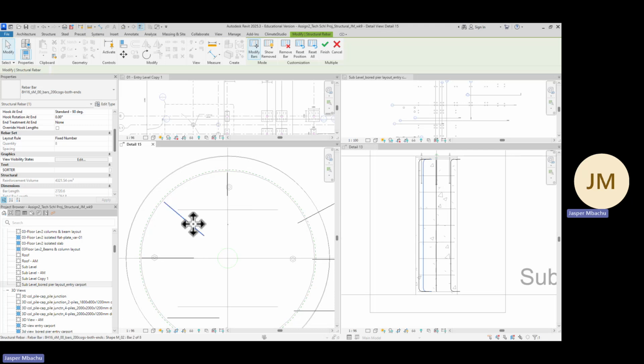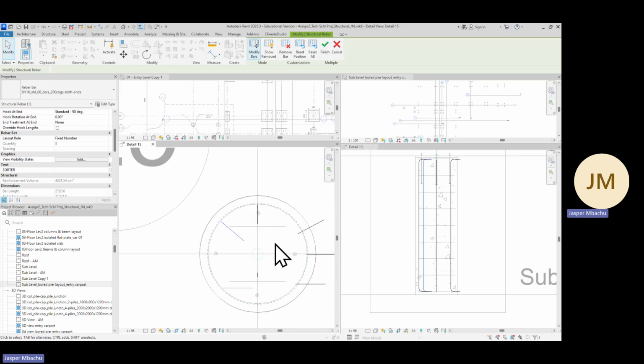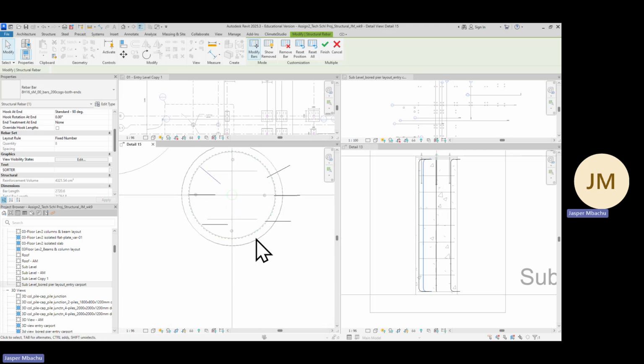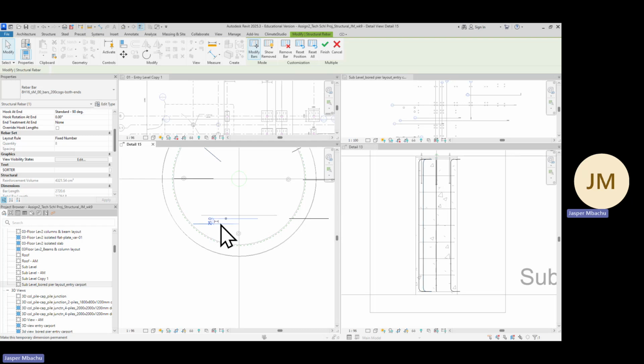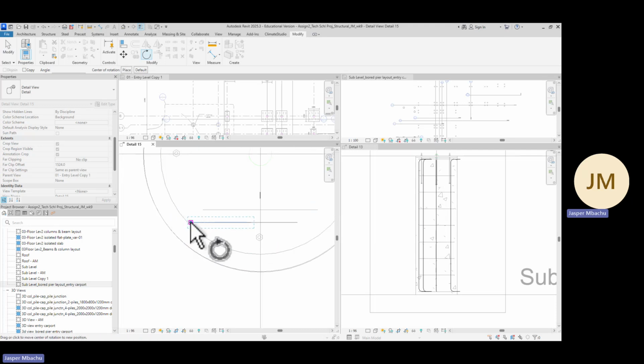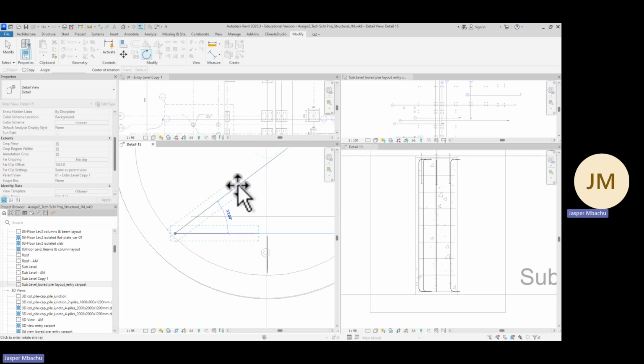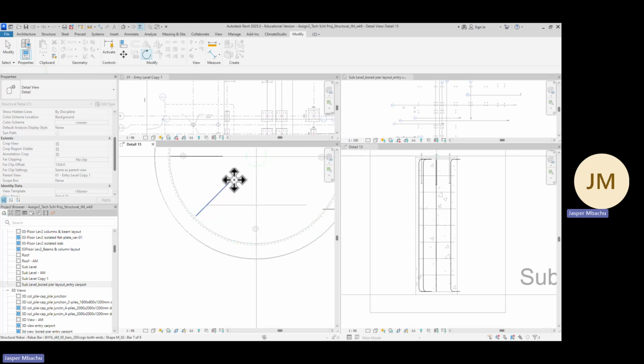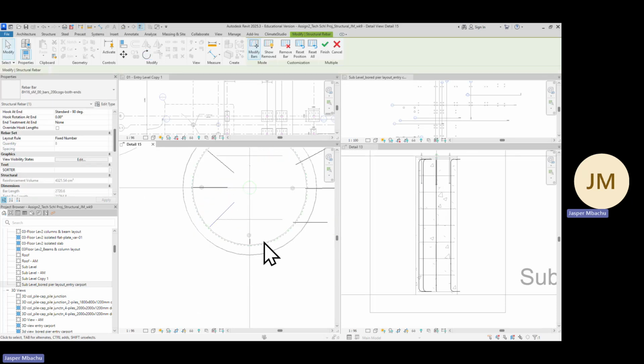Click. So it obeyed me here, but it's not always obeying. Let me do this other one too. If I click here, rotate, I will click spacebar, come to the base where I want to start that rotation, which is somewhere here. Click, identify where it was going before, click, and then I will make it point this way. This is where I want it to be. It has obeyed me there, which is fine.